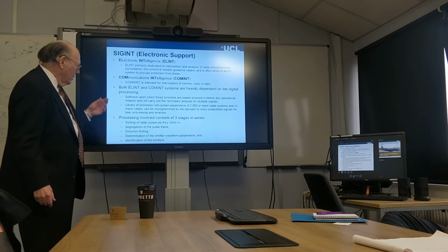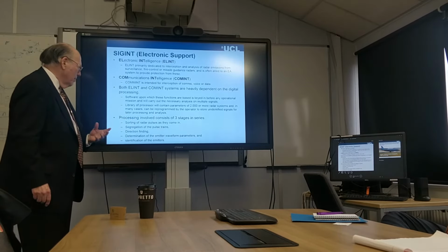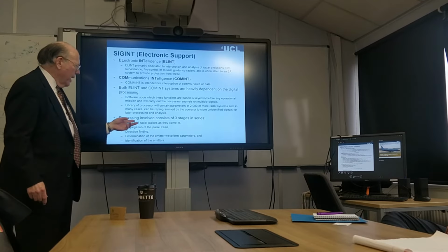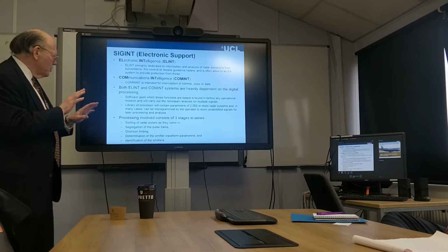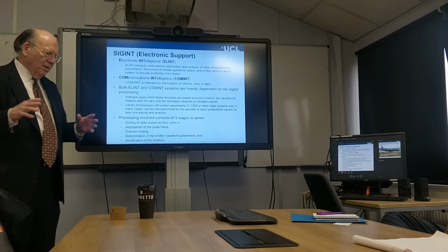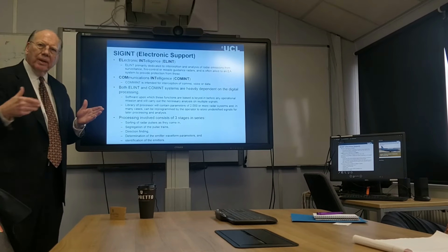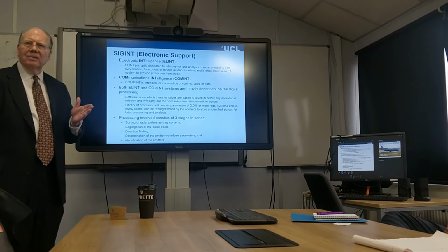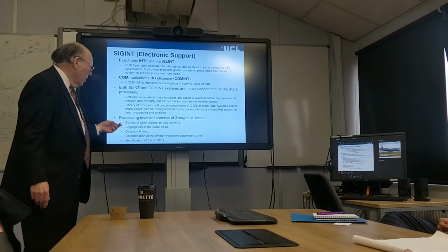So in the ELINT case, we sort the radar pulses as they come in. We segregate the pulse trains. If we're in a dense pulse environment, we have lots of different radars that are illuminating us. Then we want to be able to separate out the pulse train from those various radars so that we can analyze that particular radar. So we segregate the pulse trains.